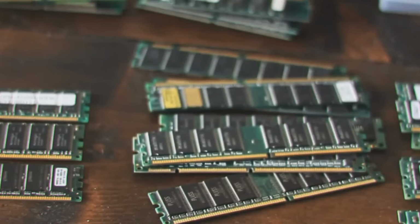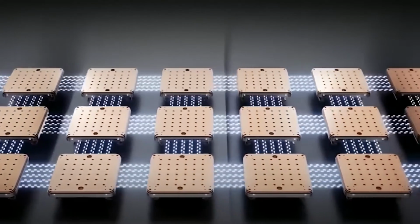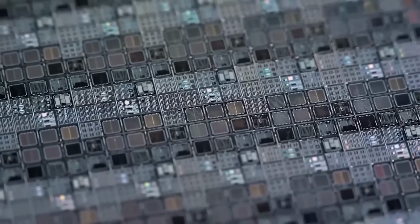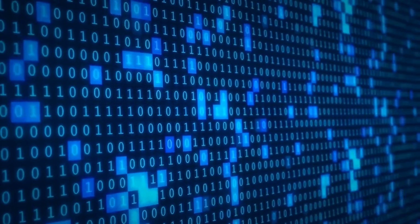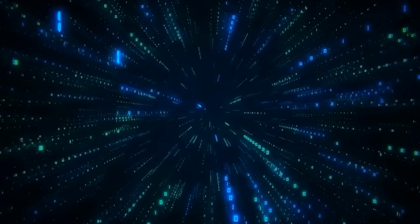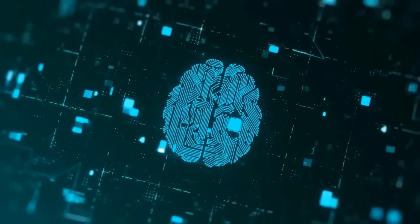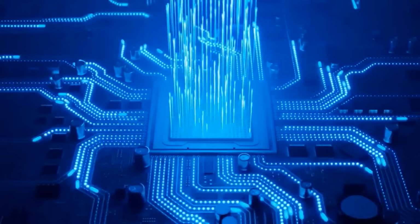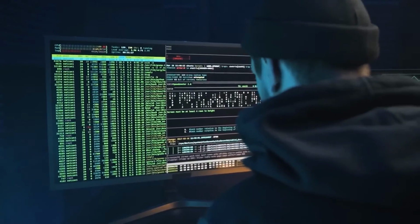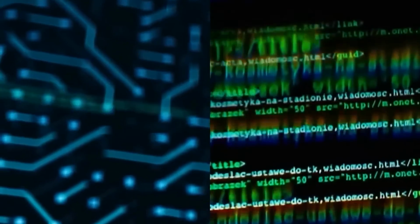So why not abandon expensive SRAM and switch to cheap DRAM? First of all, because it operates about 5 to 10 times slower. And if an SRAM is capable of providing data to the processor almost as quickly as it needs it, then when getting data directly from DRAM, the processor would spend most of its time idle, waiting for the slow memory to find the necessary data. That's why a compromise is made. Using a small amount of fast but expensive SRAM for the computer's operation, and a significantly larger amount of relatively cheap but slower DRAM, the data needed for the processor here and now is unloaded from DRAM to SRAM, just like you pour soup from the pot into the plate to eat.